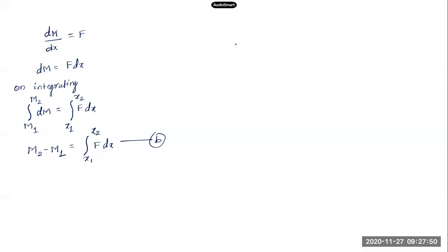So like we had the shear force diagram, you can see something like this for a beam. So if you consider 2 points on this beam, the area under the shear force diagram will be nothing but the difference in the bending moment between these 2 points. We'll see that when we take up the examples, this relationship will be useful to us over there.